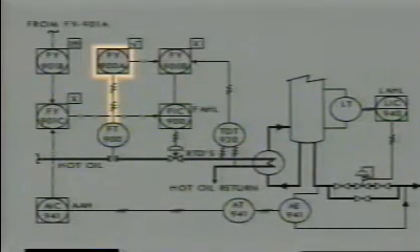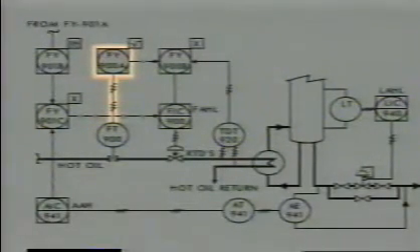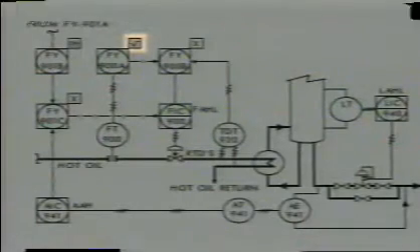The symbol indicates this is a software function in a shared controller that is not accessible to the operator. The letter Y in the functional identifier indicates that this is a computation function. The function flag attached indicates that the computing function is square root extraction.